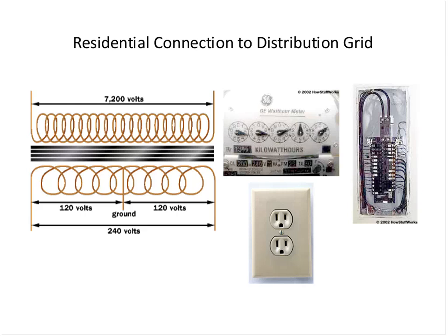Now, if you didn't have a switch, basically whatever is making the contact is where all the current will keep going until it catches fire because of the ohmic heating. So you have to be very careful. Instead of putting in fuses that just blow up and then you have to go replace them, switches are a more elegant way of dealing with it, because the switch will just open, and then when the short is fixed, the switch can be put back.